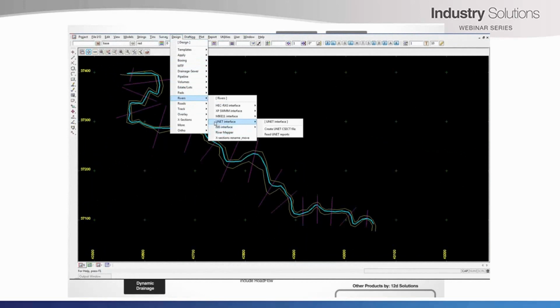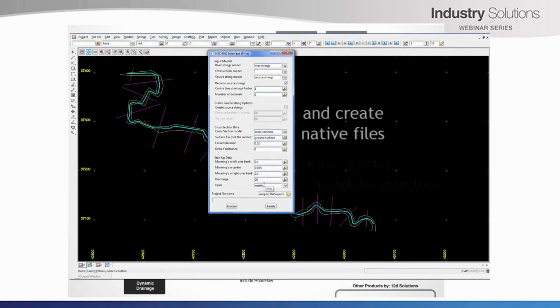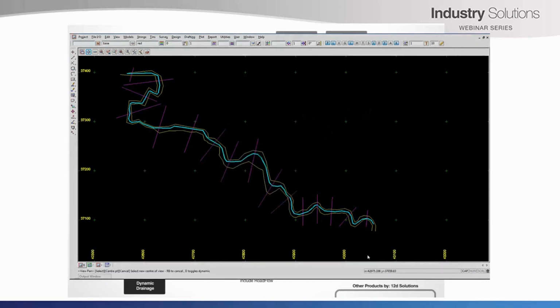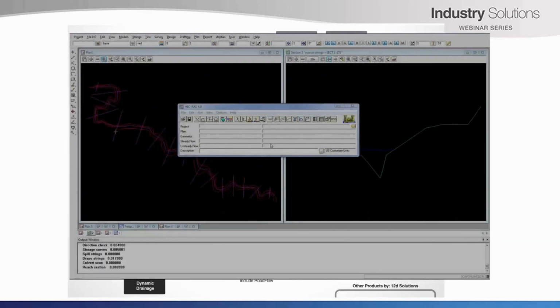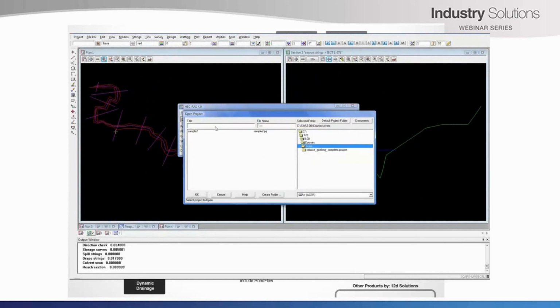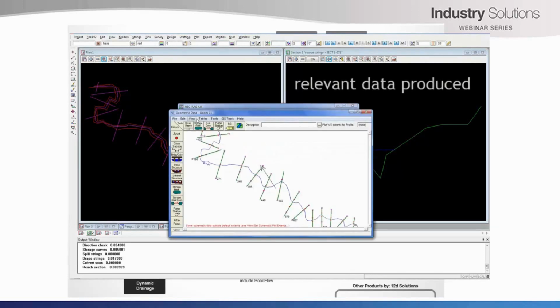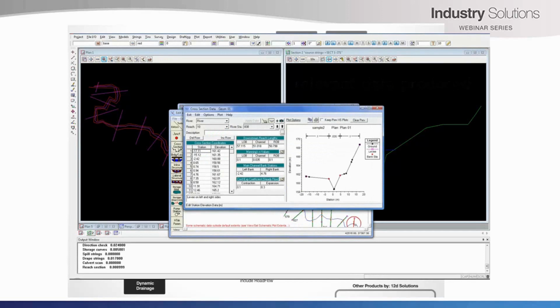The user specifies the river centerline, overbanks and cross-section, straight line or bent locations. 12D model automatically determines river levees and exports the 3D river system to programs such as HECRAS, Mike11, UNet, ISIS and XP Swim. ISIS and XP Swim storage reservoirs receive stage area curves directly from the surface tin.